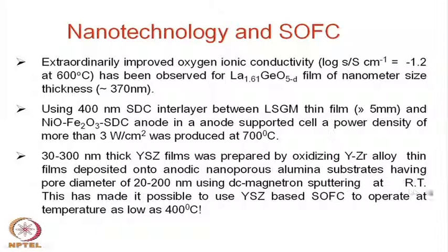Okay. So, this is a little exotic process. Commercially it may not be economic to do that, but just to demonstrate what kind of advantages we get by thin film sputtering and so on. So, one can make in fact micro thin film SOFCs like this. This has made it possible for YSZ based SOFC to operate at a temperature as low as 400 degrees centigrade. So, below 600 is very difficult, but with this kind of exotic materials or exotic fabrication technology, the temperature of operation can be as low as 400 degrees centigrade.